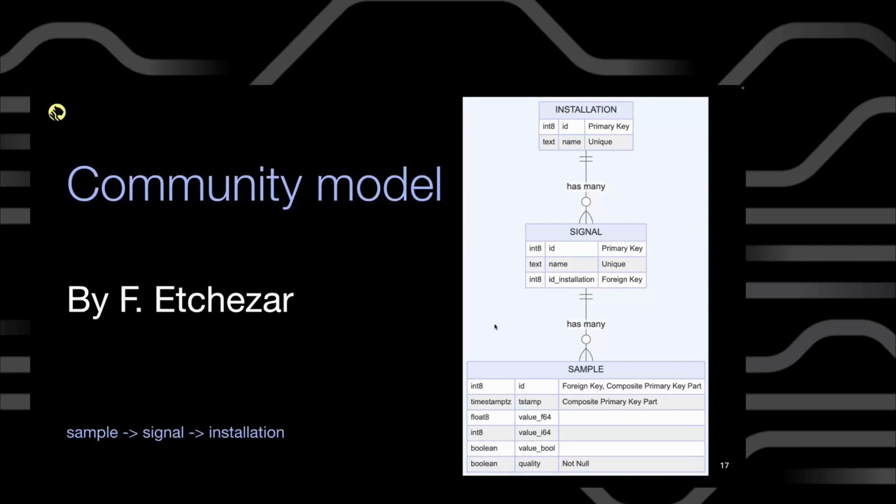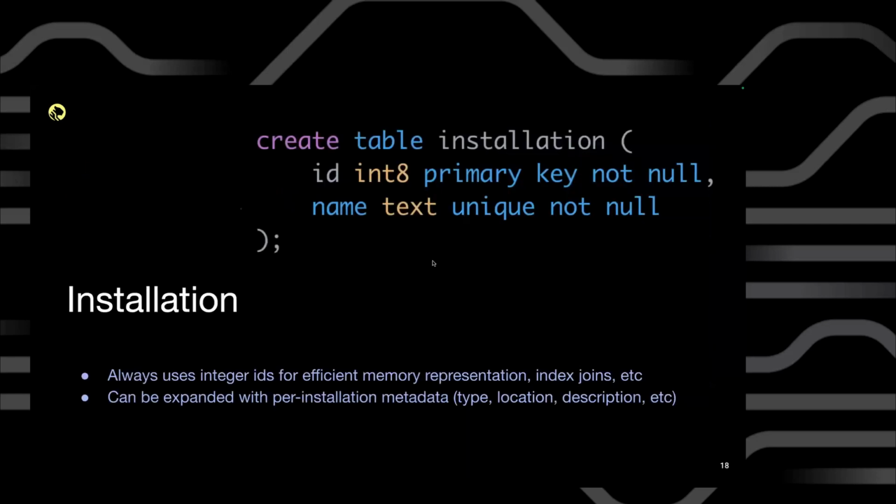This is like an abstract view of our base model. Installations are quite complex in oil and gas. They have a lot of distinct parts, and they use a lot of industrial protocols, which are quite expensive. So not all of our solution is open source and free. Specifically, the part that connects to the installation in the field is a proprietary gateway that understands all the industrial protocols like OPC, Modbus, etc. So all of that isn't done by your usual MQTT or some free tool, but rather that needs quite an expensive piece of software to connect to the field.